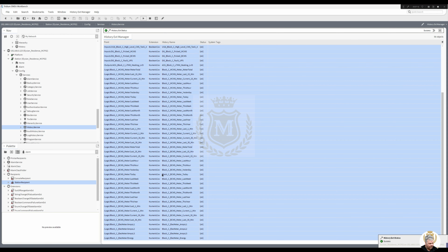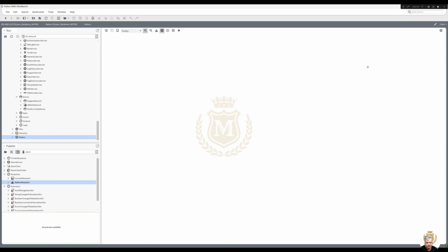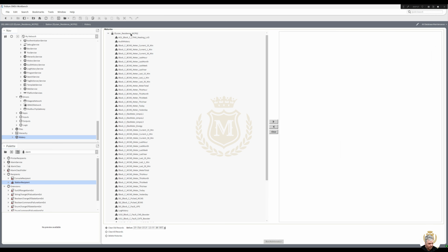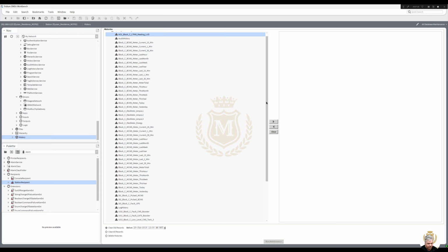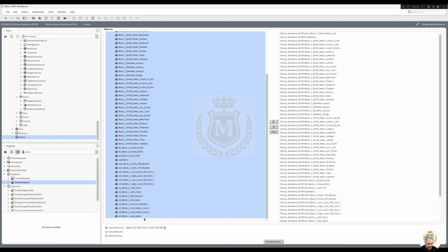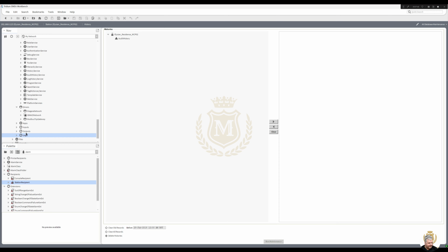But I may have some histories with the old names. So what I'm going to do now is go into my history service. Click up at the top here, chart. Click database, or AX database maintenance will do. I'm going to select all them histories, move them across to the right. Click on delete histories and run maintenance. Yes. So that would delete all the histories, and any new histories starting will populate on that side. So we've got a nice clean slate now.